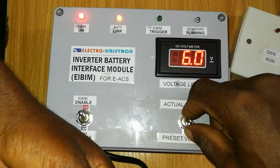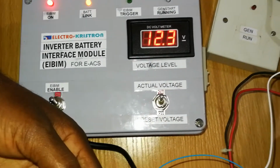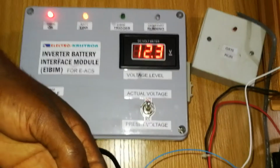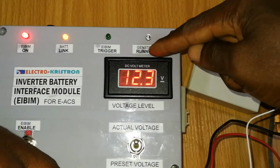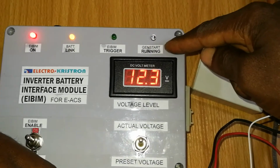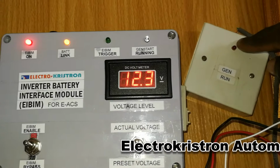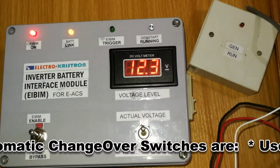Now, based on our discussion earlier, we said that the moment the actual battery level drops to the same value as what you have on the preset, or a bit lower than the preset, the gen will kick in. The gen start signal will come up, and then the ATS will sense that there's need for it, or it's now meant to start the generator.